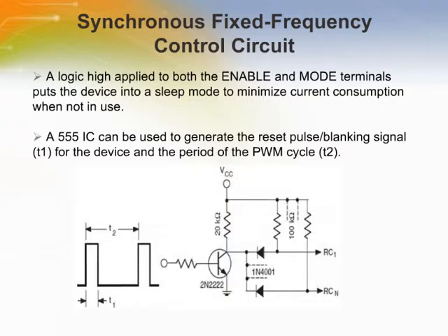The phase and enable inputs should not be pulse width modulated with this circuit configuration due to the absence of a blanking function synchronous with their transitions.